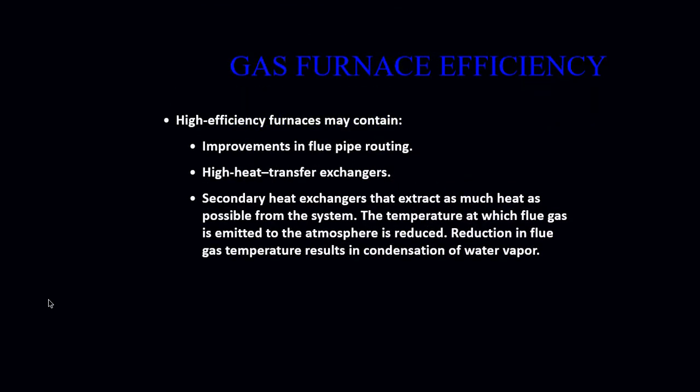Your high efficiency furnaces may contain a couple of different varieties. They will have an improvement in the flue pipe routing. They are going to have a high heat transfer heat exchanger in them. They are also going to have a secondary heat exchanger in there. And that secondary heat exchanger extracts as much heat as possible from the system. The temperature at which the flue gas is emitted to the atmosphere is also greatly reduced.